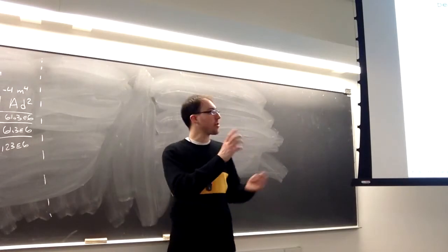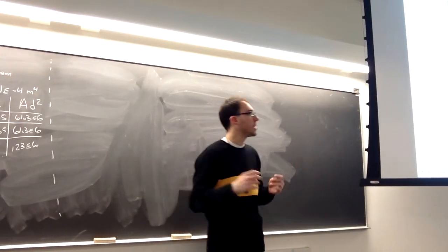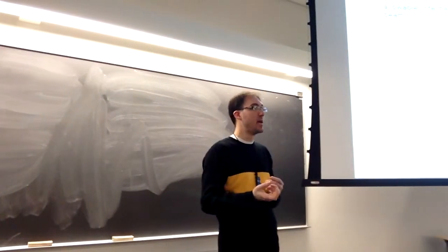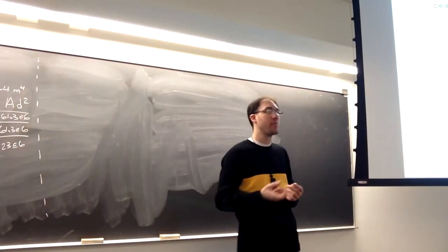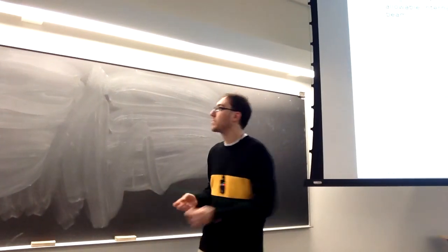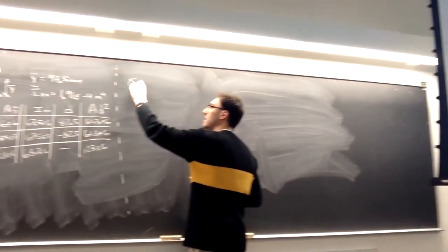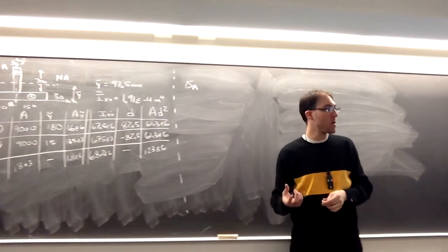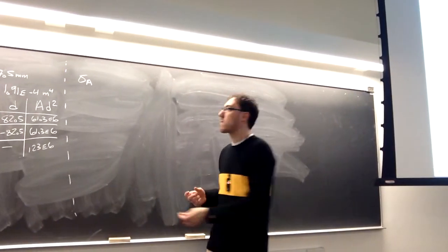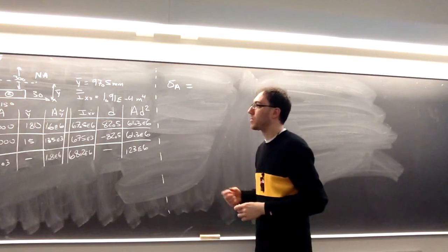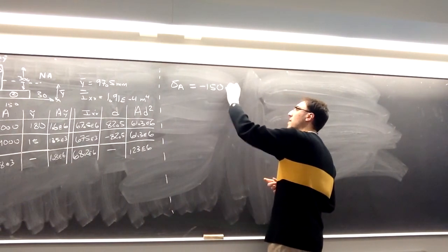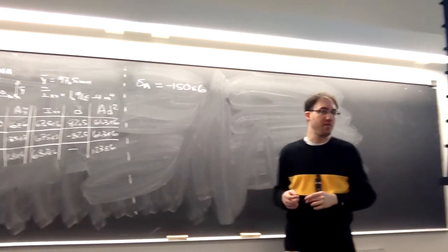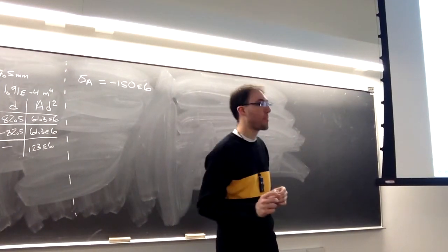Right, so from the picture, if M is in the direction as indicated, A should be in compression. And you're right, we want to check A because that's where the highest compression anywhere in the beam is going to be. So if we're not exceeding the compression there, we're not exceeding the compression anywhere. So we can set A equal to the maximum compressive value. We want to make sure we pay attention to the sign here. So negative 150 megapascals, since A will be in compression.